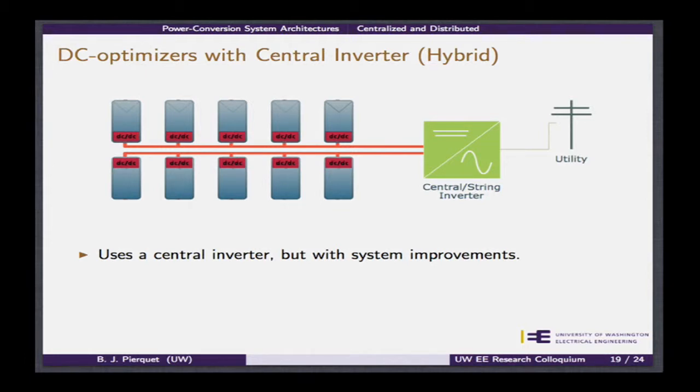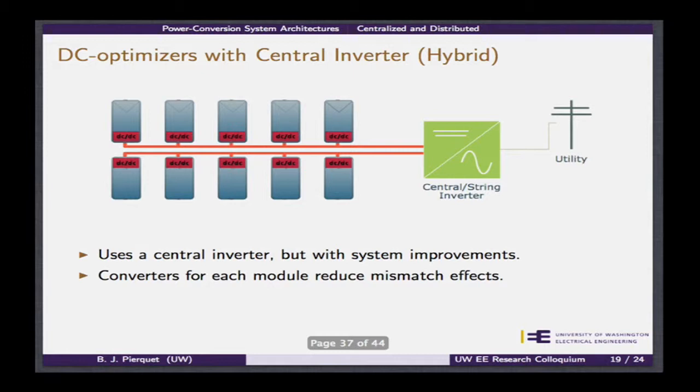Well, when you have these distributed architectures, you get the maximum peak power out of each module. Now, if each module has its own internal mismatches, there's not a lot you can do when all you have access to is the output terminals of that module. But this essentially allows you to get pretty close. And so this has allowed some of the residential installations to avoid doing microinverters. Residential installations end up with lots of shade. And so in that case, these will allow the different modules to perform close to their peak versus essentially dragging down the whole array with a centralized inverter.